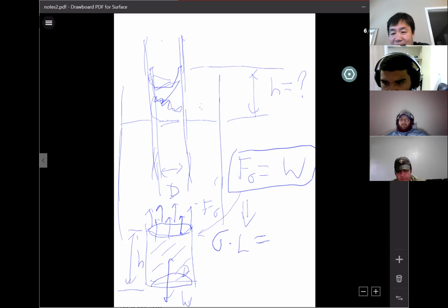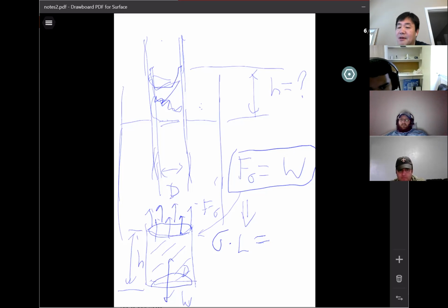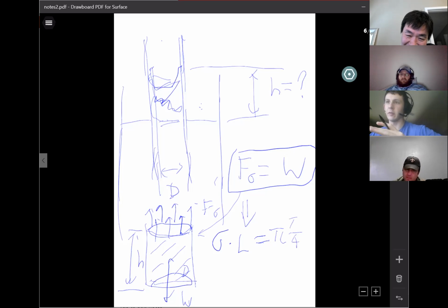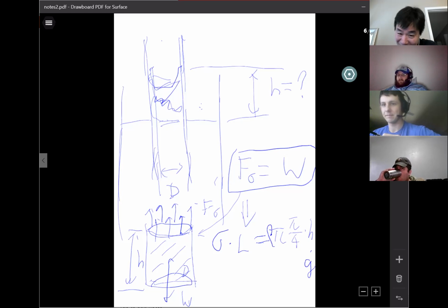The diameter is D, right? Do you know how to calculate the weight of a cylinder? If you cannot spit it out in 5 seconds, then it frustrates you. It becomes a difficult problem to you, right? Is it pi d h? Hold on. It's pi over 4 d squared to get the surface area, then times h to get the volume, times the mass to get the weight. That's what I meant. Volume times density, then times g. My bad. See, don't make mistakes on that.